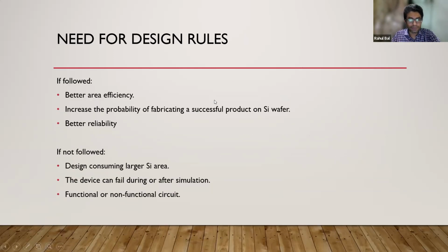So why do we require design rules? If design rules are followed, we can achieve better efficiency, increase the probability of fabricating a successful product on the silicon wafer, and your circuit will have better reliability. So those are the advantages of using design rules.